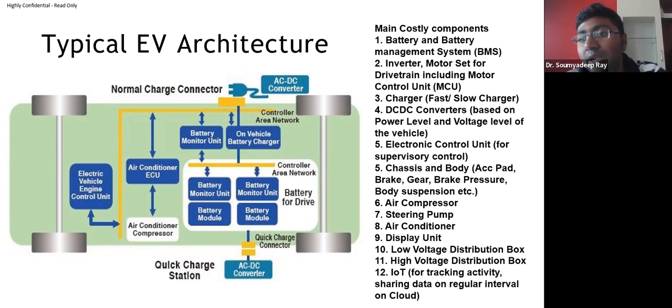Not only that, from a safety point of view, suppose you have one 3-phase inverter; in one leg there would be 2 MOSFETs or 2 IGBTs. These might get short circuited or overheated. This is a very dangerous and critical scenario.